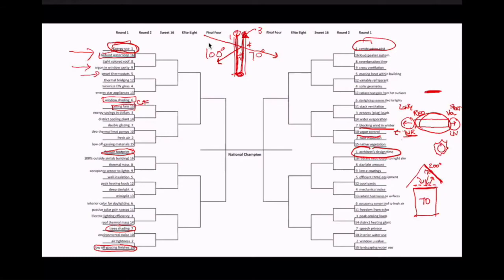Foil is a tricky one when it comes to moisture, because if you have foil, you're not allowing moisture through, and moisture can get trapped if there's a second barrier to moisture. So that's why you ventilate it. In this case, the whole attic is ventilated, so if there's ever even a tiny leak, which there will be on a windy day, it's a sloped roof that relies on lapped shingles, and sometimes wind blows water underneath the shingle, and a tiny bit of water will get in here.